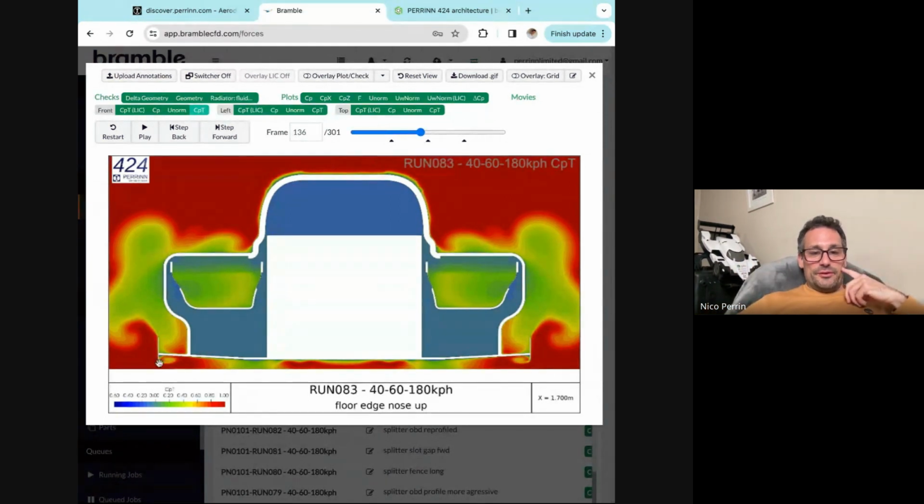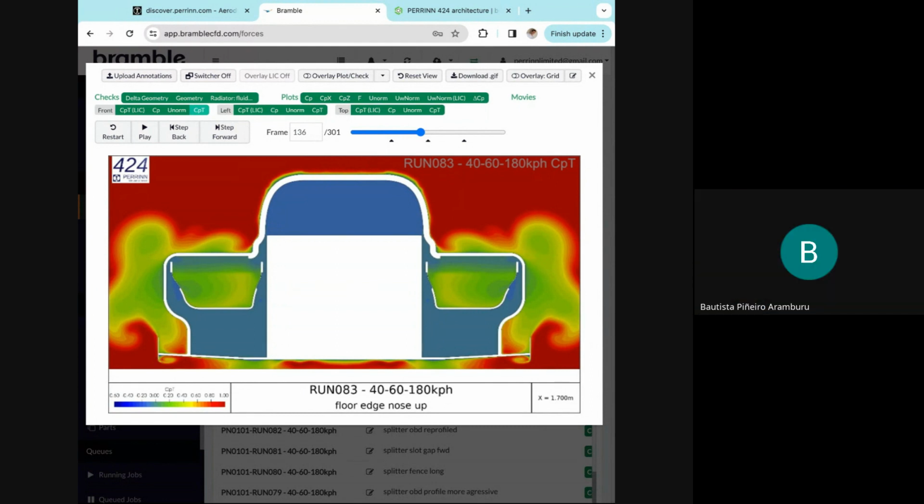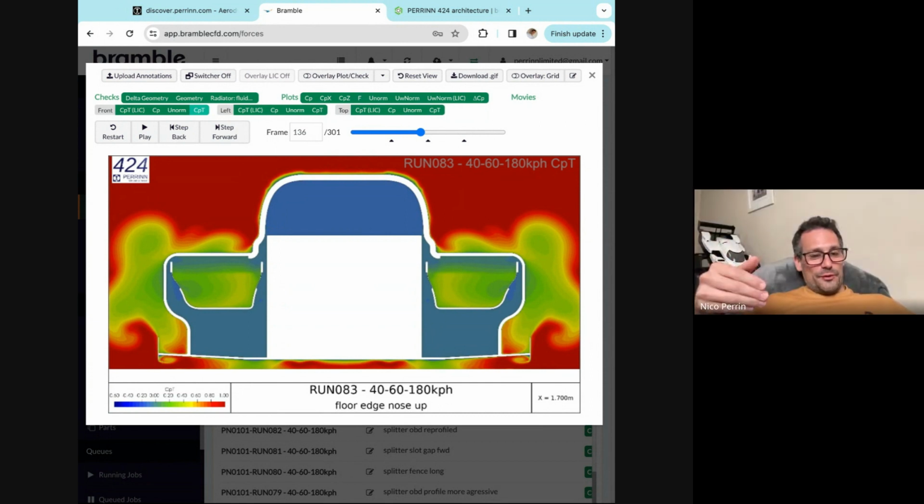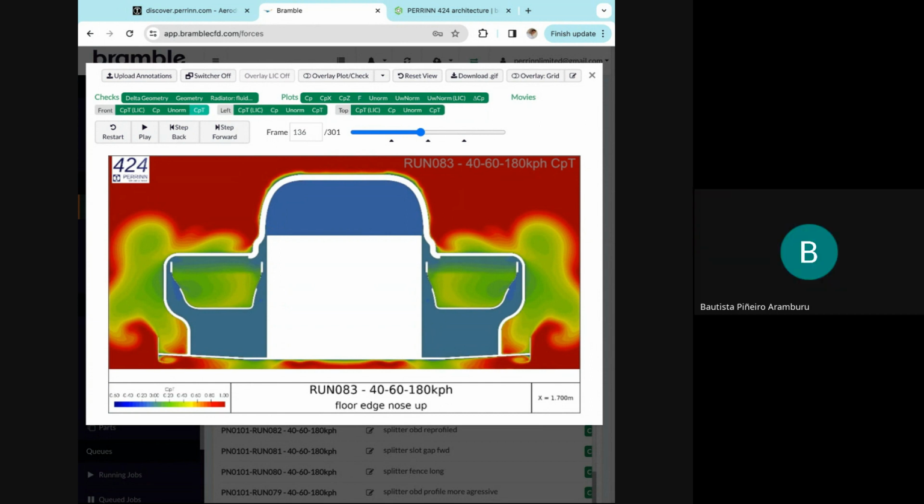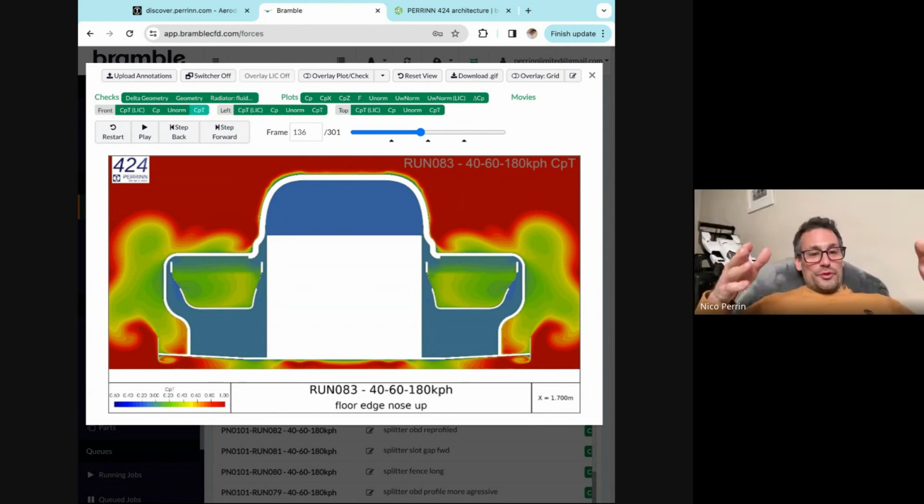And that's why we have fences here, or the famous skirts on the old F1 cars. You can see the effect it has, because air wants to enter anyway from the sides. Yeah, exactly. And what you do is you're not going to change that, because it's a whole pattern of suction and high and low pressures. It would take a completely different regulation set, or to remove the wheel arches to change that, and you're not going to do that.